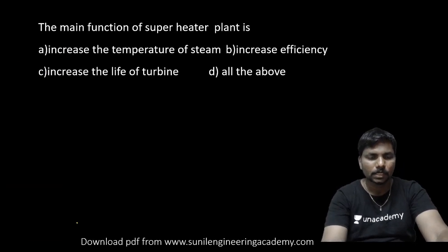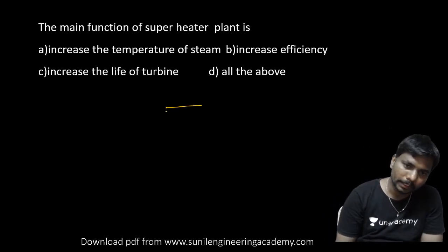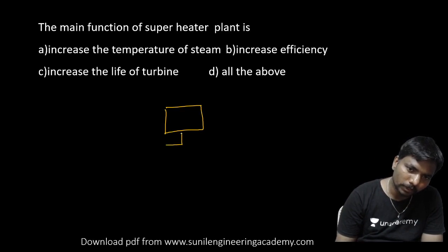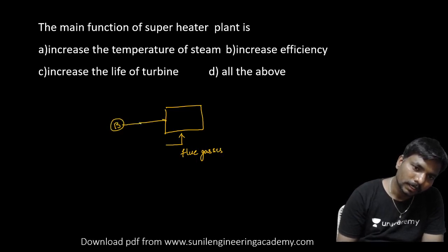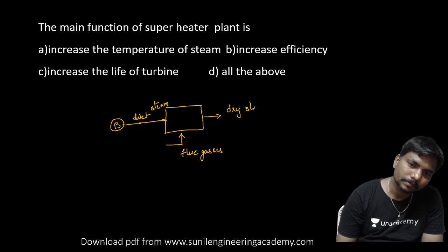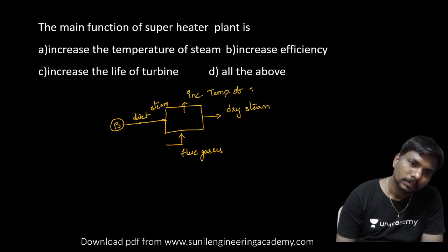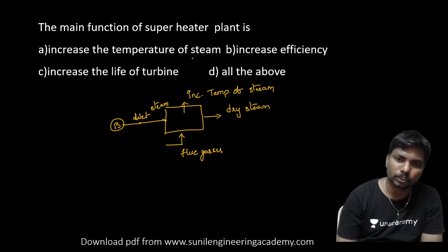Coming to the next one. The main function of the superheater is dash. I already said what it will do. The superheater utilizes the flue gases heat. From the boiler you are getting wet steam, and that will be converted into dry steam. So it increases the temperature of steam, so the first point is correct.